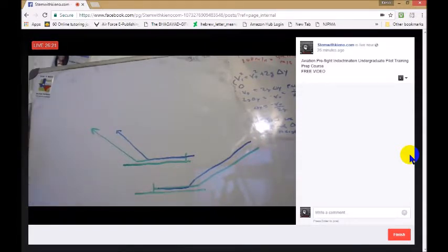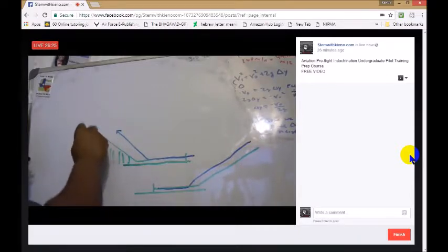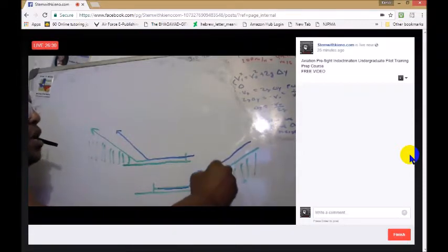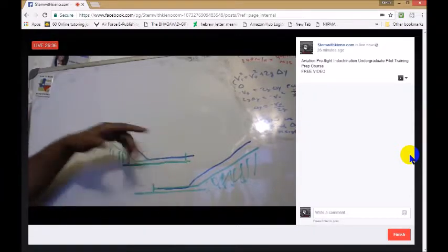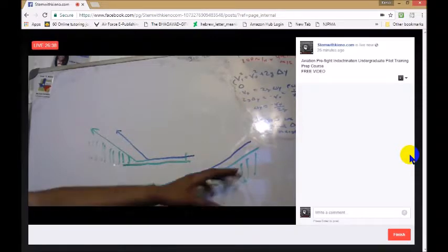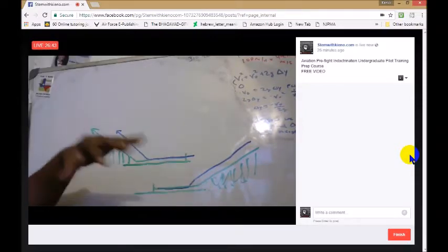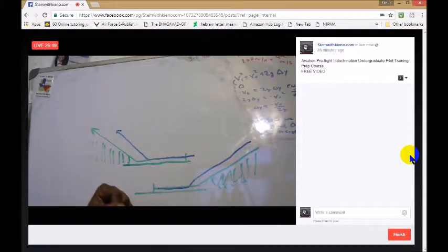Because the whole time that this aircraft is taking off, the wake turbulence is going to be here. And when the aircraft is landing, the wake turbulence is going to be here. And let me tell you something, ladies and gentlemen. The wake turbulence will rock you a little bit. All right, so you definitely do not want it in this scenario when you're landing. You already have to deal with crosswinds, things of that nature. And then you're coming in to land, and you mess around and you get too low, and that could be an issue. All right, as far as directional control.